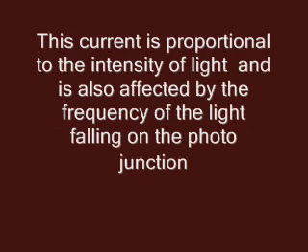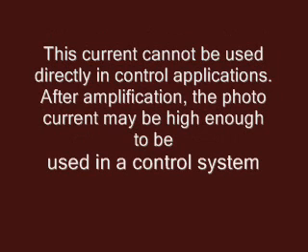This current is proportional to the intensity of light and is also affected by the frequency of the light falling on the photojunction. This current cannot be used directly in control applications. After amplification, the photo current may be high enough to be used in a control system.